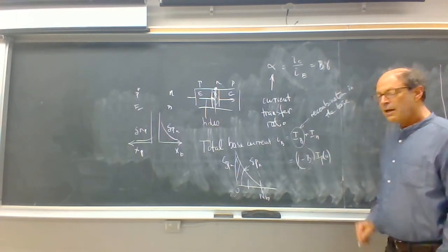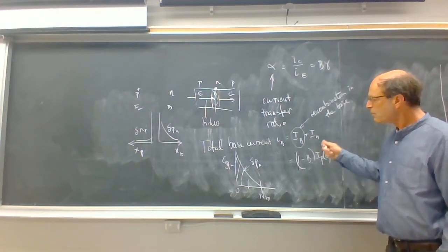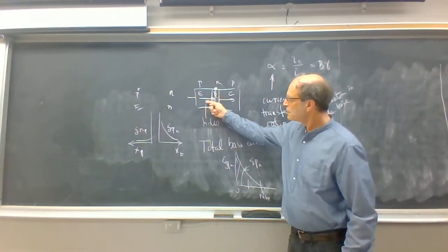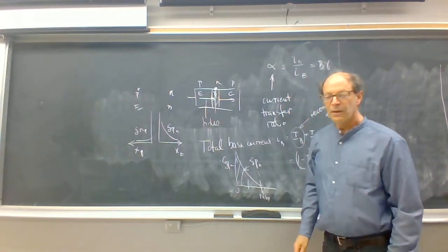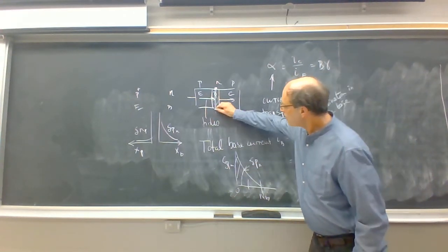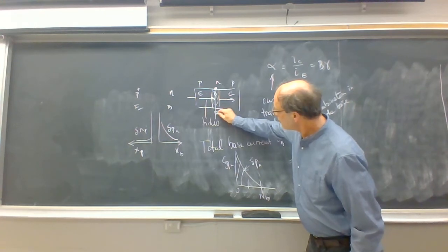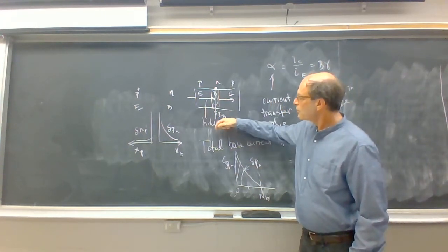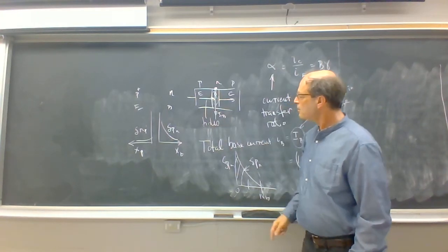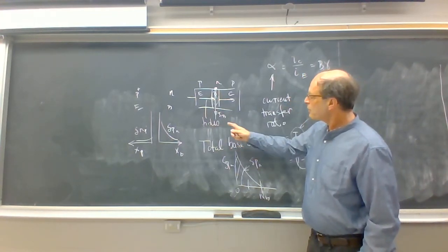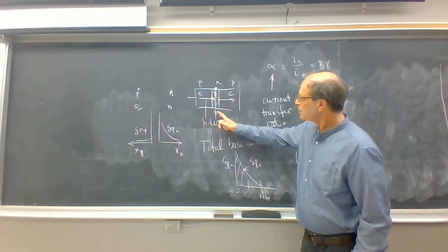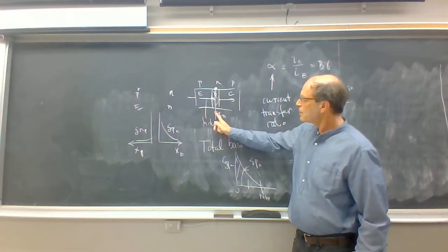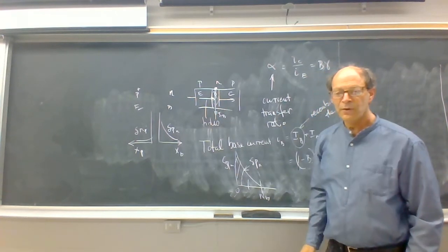And that difference will represent the base current, which is the recombination within the base. And I'm going to then add I sub N, which is the other source of base current, which is base current that leads to the injection of electrons into the emitter. Both base currents, incidentally, flow in that direction, because current flow this way means electrons injected into the emitter, and it also represents the recombination of holes in the base as electrons enter to resupply those holes.